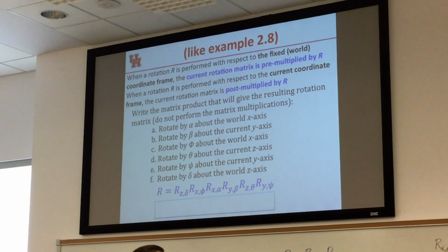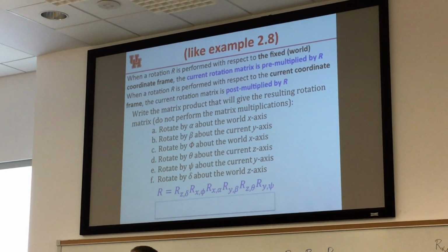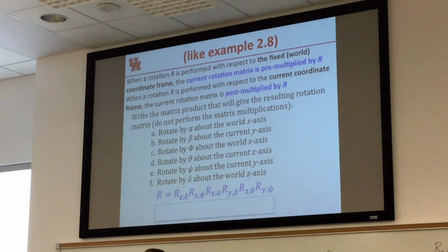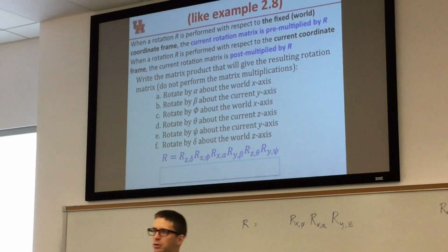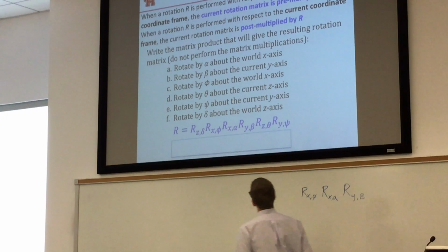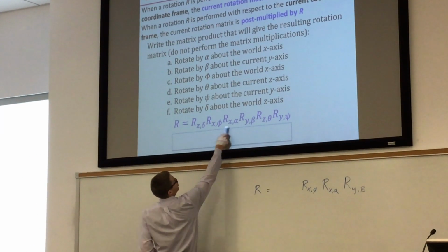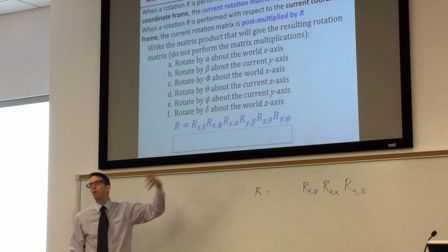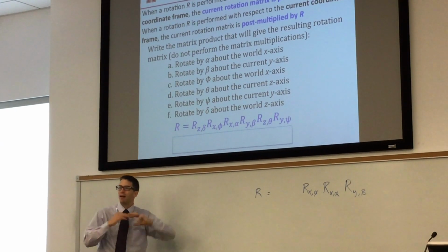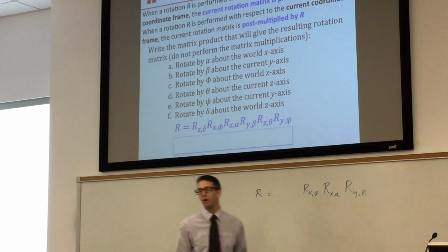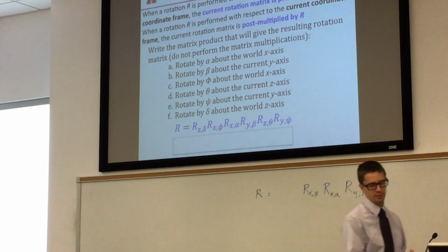Yes, I want you to look for if there's any two rotations that are on the same axis. You're looking at it, objectively, you can't tell the difference. Those things sum together. That simplification is too easy to do. And so you can see that I got z and then I got two x's that are right after each other. So we can simplify that. That's a total rotation around the x-axis by alpha 5 plus alpha. And that's what I want to see on your exams.